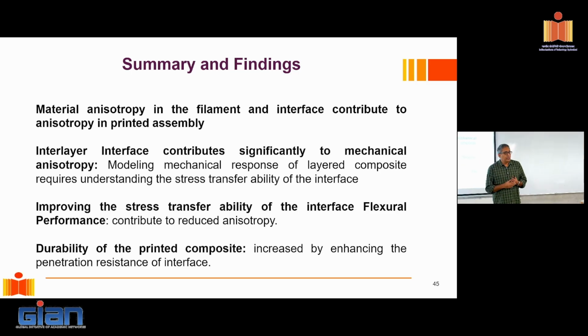So, what are we talking about when it comes to printed structures? Well, we have this structure which is made up of layers. Some anisotropy is bound to happen. The reason is I have these layers. So now the stress transfer between the layers becomes very important in determining the strength of the printed filaments. And as I concluded in the last few slides, it's all about the shear stress transfer across those interfaces that are formed between the printed elements. And we can go down to that level and start coming up with predictive equations.